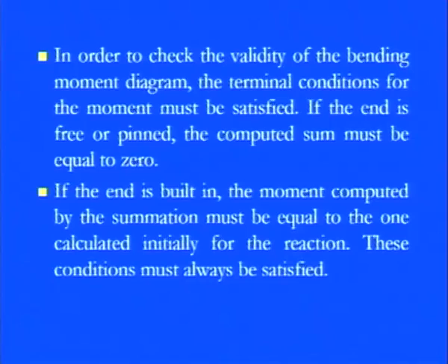If the end is free or pinned, meaning the reaction forces, the sum of all the components under the application of these forces must be equal to 0. That means whatever forces are coming in, as I told in the individual section, must be well balanced, and we can say that the pinned or free end is simply inducing the bending moment equal to 0.